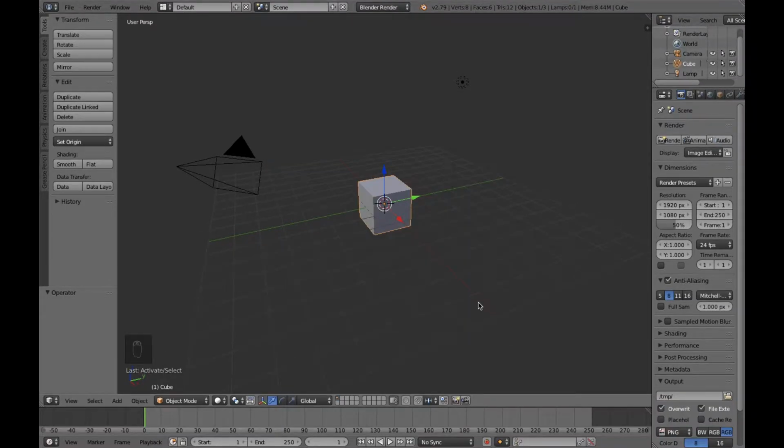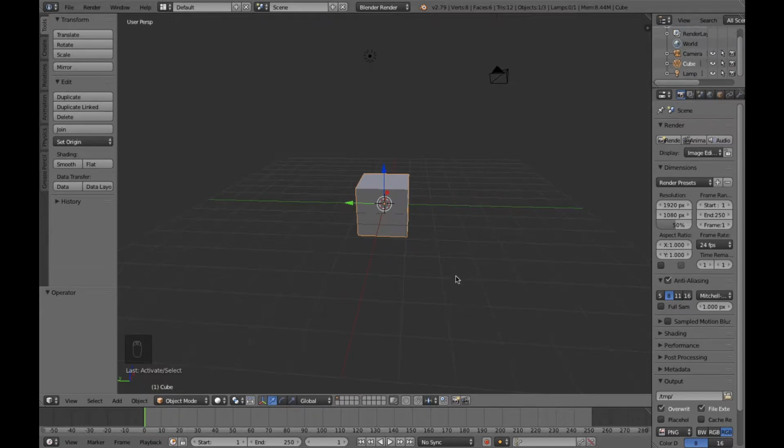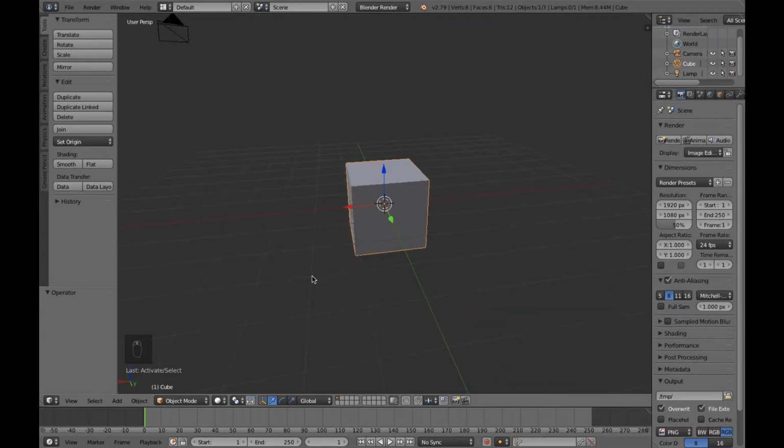So once you've opened Blender, you're often provided with a cube, and you can zoom in and zoom out by using the scroll wheel, and you can turn the object along any free axis by holding down the third mouse wheel button. It's always important to use a mouse while doing 3D modeling because it becomes quite necessary for actual and proper 3D modeling. Also, I've turned on a feature which you might or might not want. I'm not going to show you how to do that, but the feature is basically whatever I press on my keyboard or my mouse is shown on the screen, so that you can follow along sometimes if I forget to mention what I'm pressing.